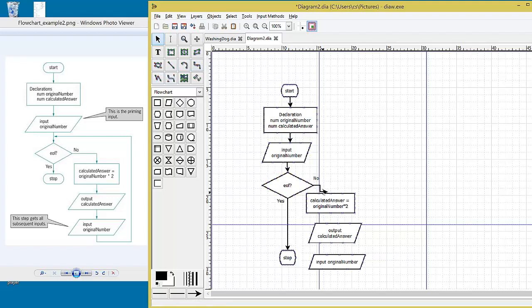Again, you can see sometimes the arrows kind of behave strangely. But every time it doesn't work the way that you want, make sure you add a segment and then remove segments that you don't need. And you can see, you can quickly fix the zigzag arrow to point the right way. And many times, if you just need a straight line, don't try to use the zigzag, just use the straight arrows. You see, if you connect the arrows to the middle of the shape, they align nicer.